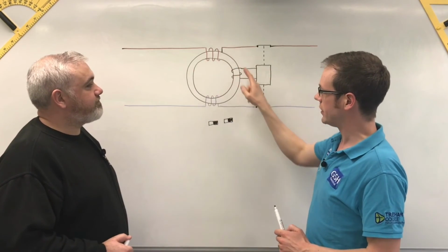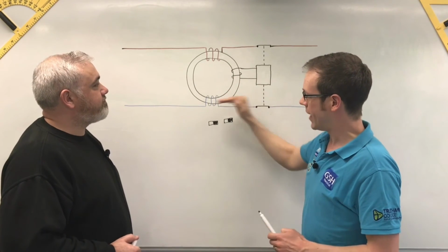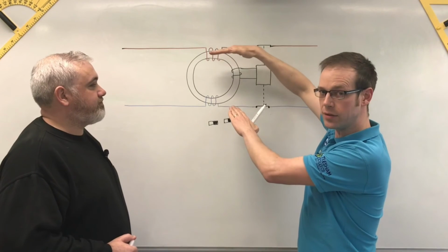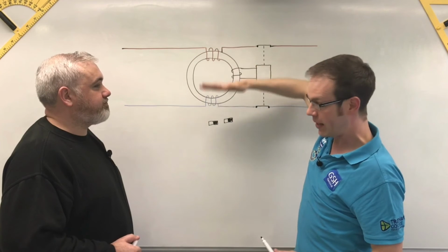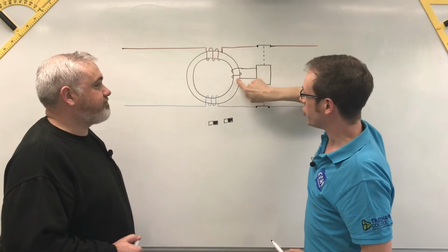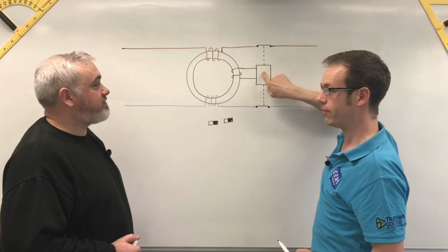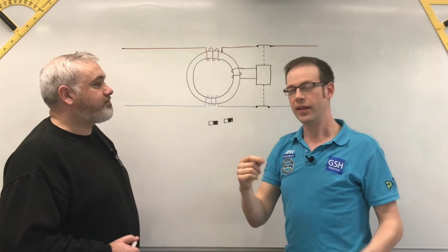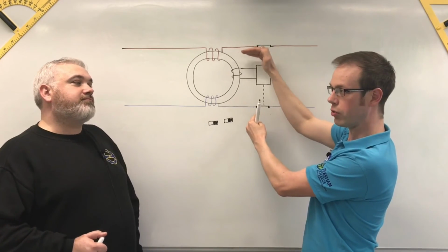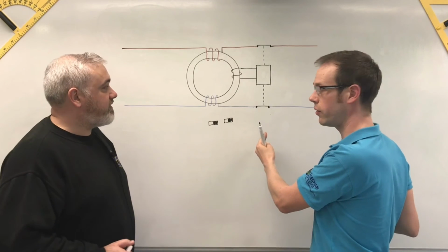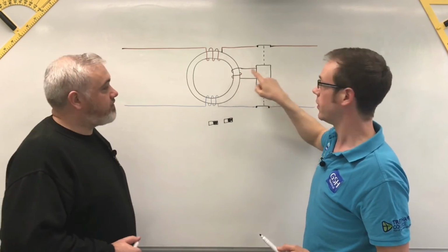because this iron core is still slightly magnetised, there is not enough magnetism generated by the imbalance in the two coils to fight against that remaining magnetic field and generate enough current inside this coil to trip the RCD. Absolutely. And that is the big problem. The RCD has to generate a much higher imbalance between the line and the neutral. There has to be a bigger flow of current to earth to generate the tiny amount of current that is required to trip the RCD.